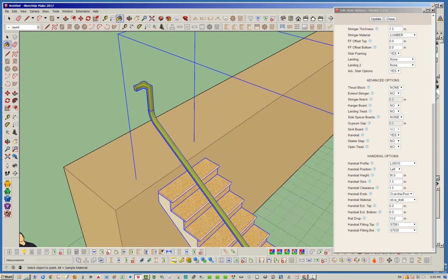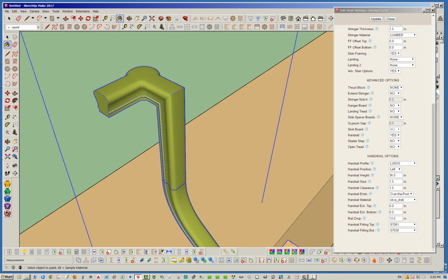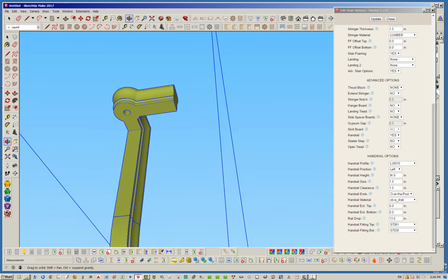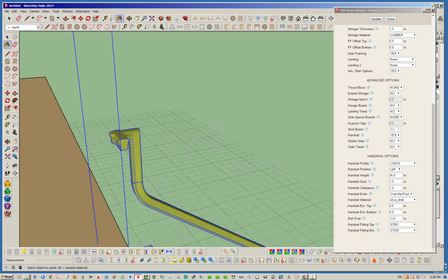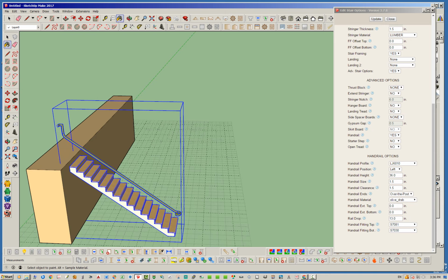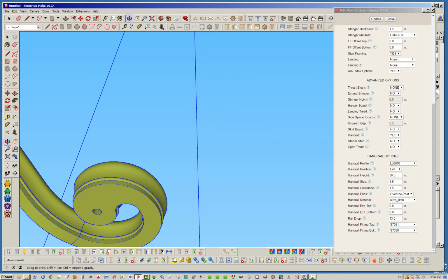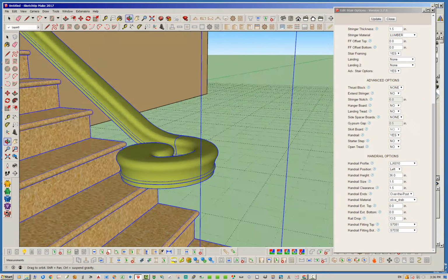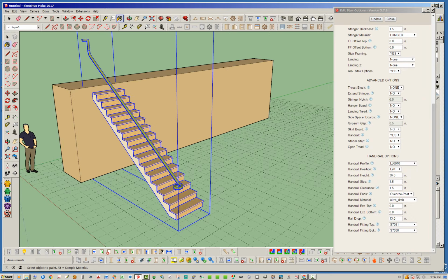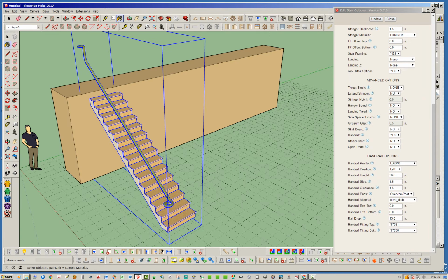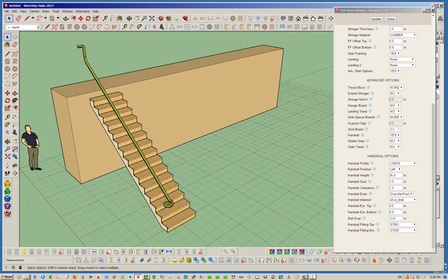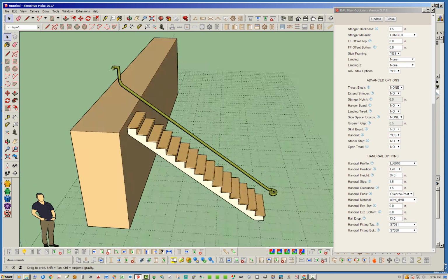Okay, so there you go, and that typically has a balustrade, or not a baluster, a post right there, and then this of course terminates with a post as well. You'll see there's a 3/4 inch hole, 1 1/8 inch deep, so you can lay out your stairwell and your post. Okay, so basically that is that. Now we're going to get into all these other parameters.